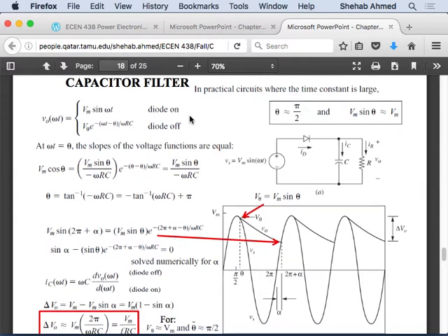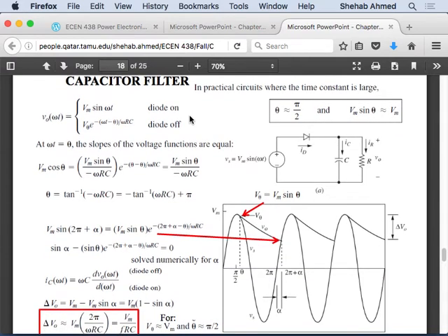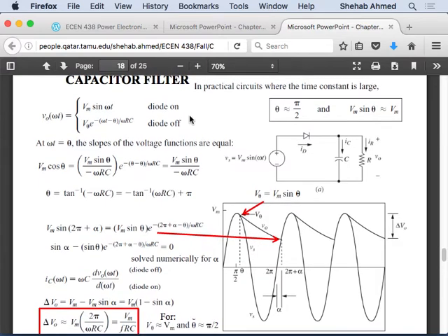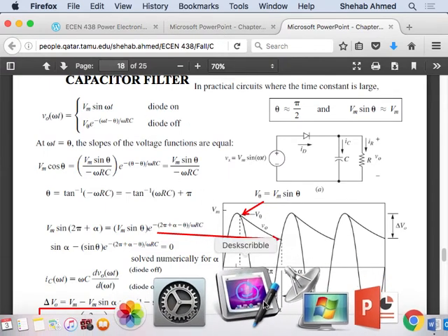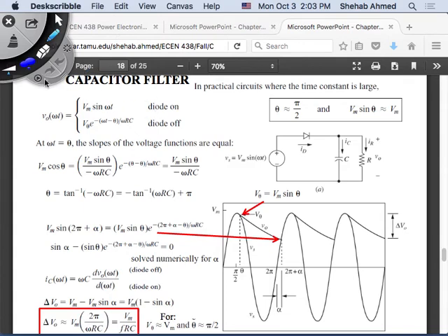Anyway, so for capacitor filters. So what did we say is happening here? Actually, what did we say is the objective of this circuit here? All of them were create DC from AC, right? But remember, we said we had a DC, or a waveform with an average value, but with a huge ripple. Remember, initially we have a half-wave rectifier. Without this capacitor, the output voltage looked like this. This is my output voltage.